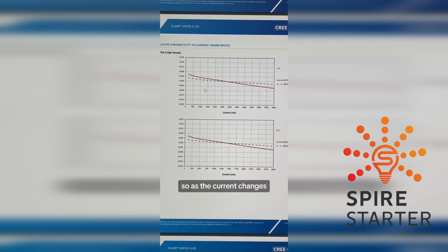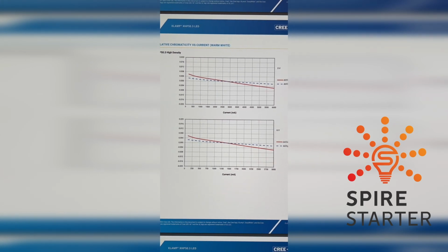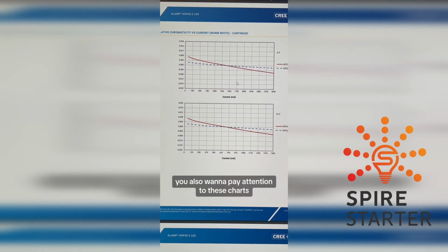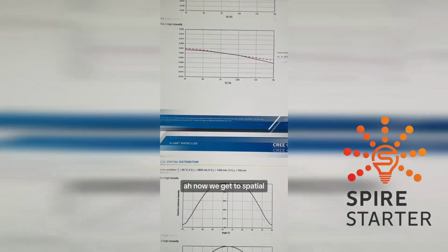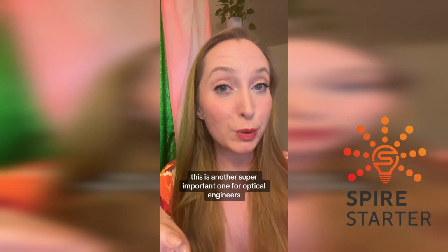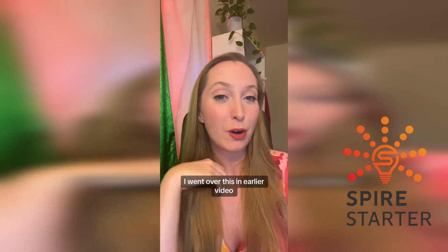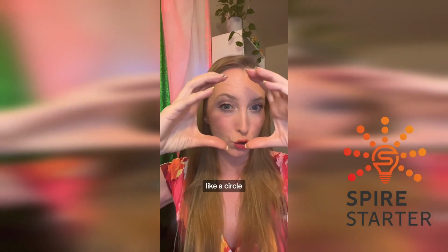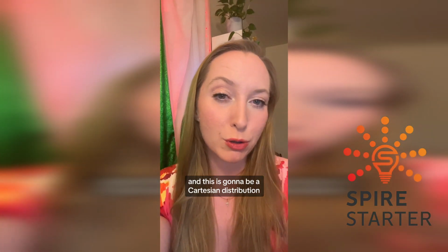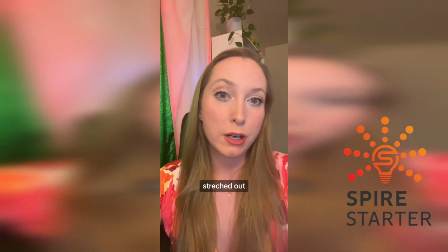So as the current changes, the color also changes. And this CCX and CCY is that XY chart that I showed before. If color is important to you, you also want to pay attention to these charts. Now we get to spatial distribution. This is another super important one for optical engineers. I went over this in an earlier video and I showed the polar plot with like a circle distribution. And this is going to be a Cartesian distribution, but the same sort of plot. Same data, just stretched out.